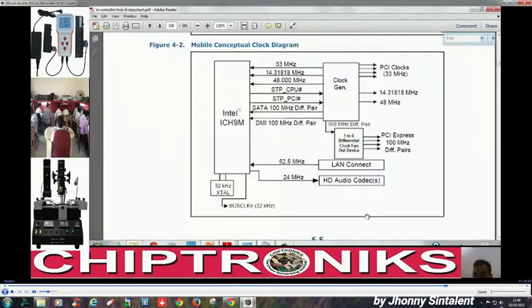So anything is governed by the data sheet. When we are discussing about the clock, what important clocks are generated, we have to see this diagram, and in this diagram we can see 2 important signals coming out from ICH to clock generator. What are those? STOP_CPU and STOP_PCI.